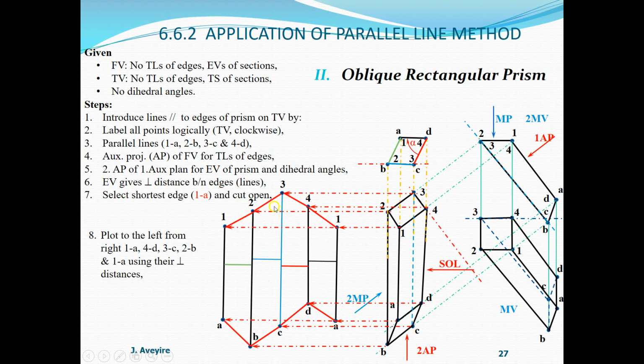These are folding edges, and the angle of the dihedral angle will tell you the angle to fold them to. Now I have that, but I don't have the true shape of the lower end of the lower opening. So to obtain that, I project perpendicular to the edge view of it over here. So I project perpendicular, that's an auxiliary projection.